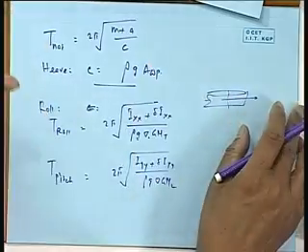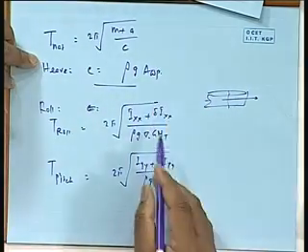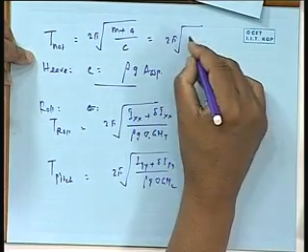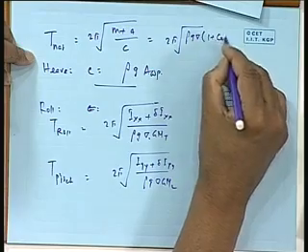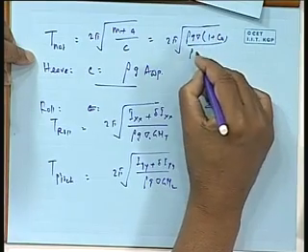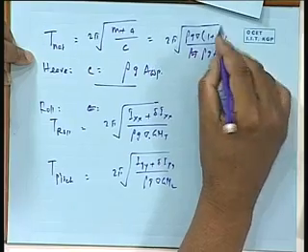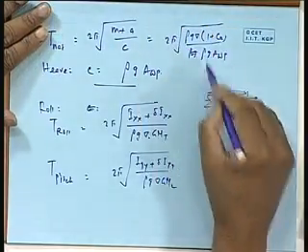Now, if you look at that, I just want to say here very, very briefly, we may not have much time. See, this has become 2π√[ρ∇(1 + added mass coefficient) / (ρ g A_WP)]. You see, look at these formulas. Heave natural period becomes something like this.